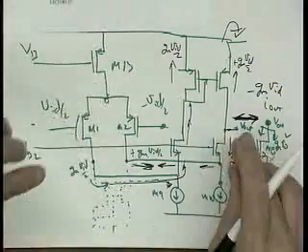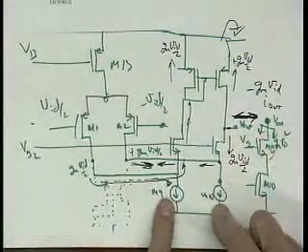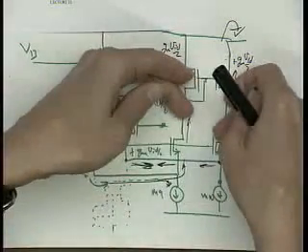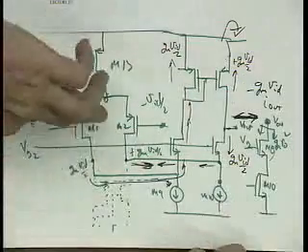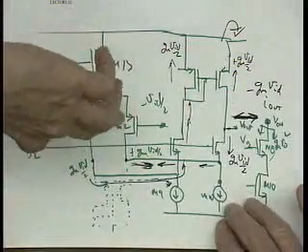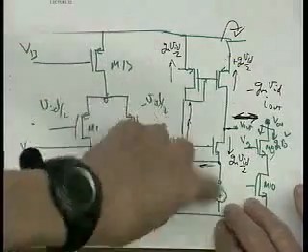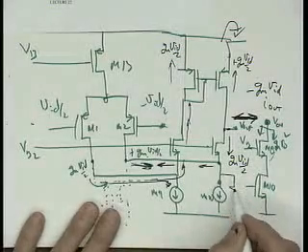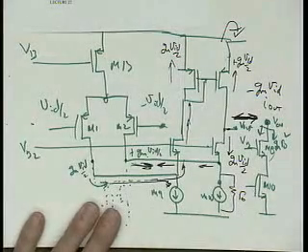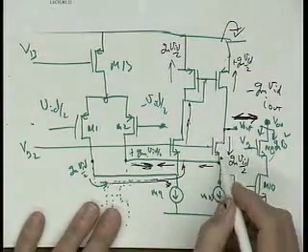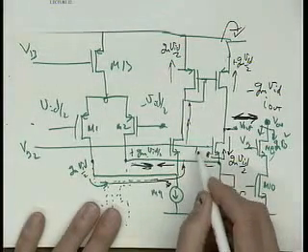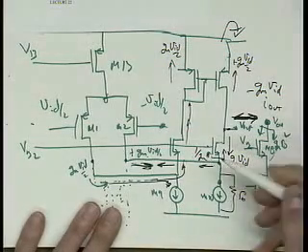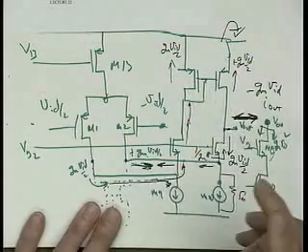So what the folding idea is, we put these current sources down here. We folded the load from here up to there. Okay? And the small signal current has got to get to ground somehow, right? It's going to go where it can go. It's basically going to be a divider going on here, right? If you think about this, this has an output resistance of, let's say, R naught. Let me finish one second here and I'll ask you. And looking up to here, I see 1 over Gm. So it's kind of a voltage divider between 1 over Gm and R naught. So you can sort of see that most of the current's going to go upwards.